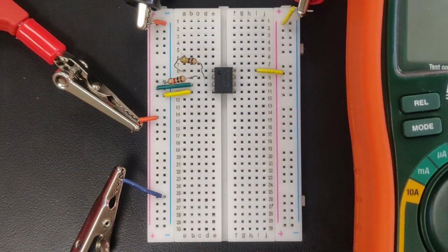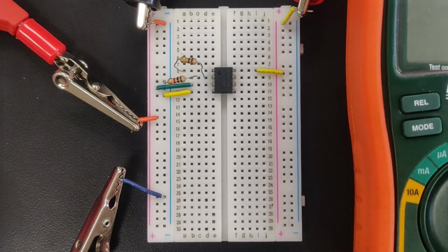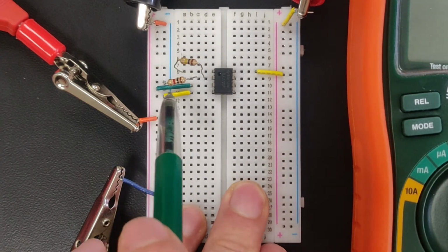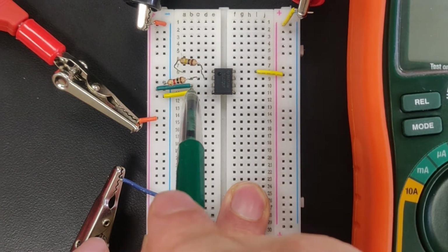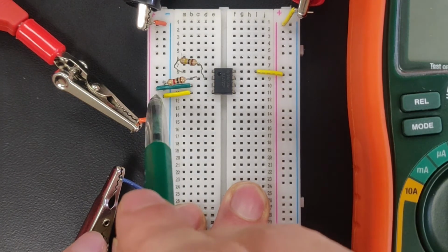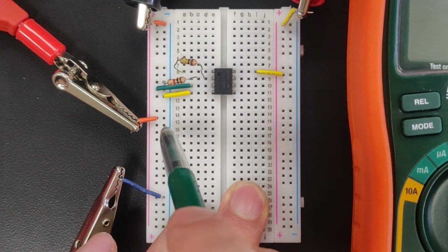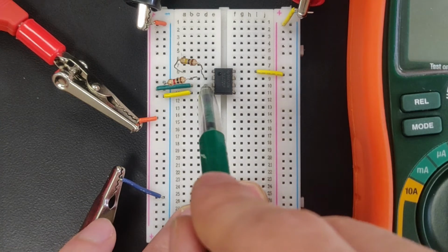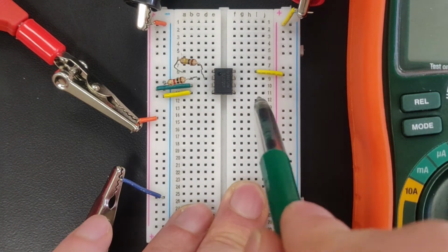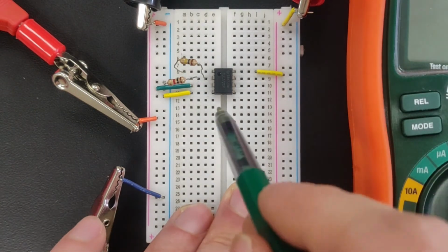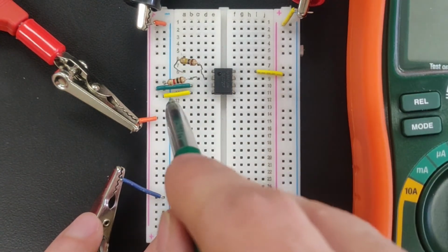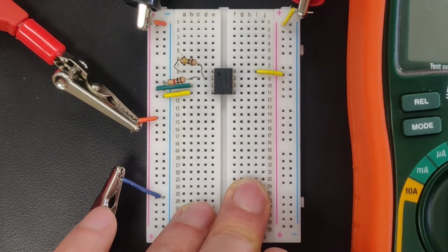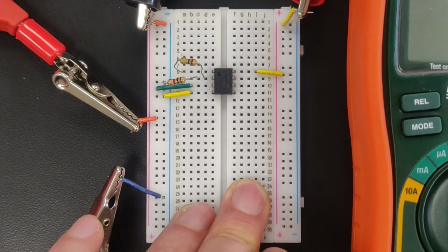All right, here is our non-inverting amplifier for part C. So, main distinctions now is that our positive Vin is being tied directly to the input, so AC input signal on the left going into our positive Vin pin. And now our negative Vin is tied to ground with this 1000 ohm resistor, and it's still the same 1000 ohm resistor from last time, so it's 985 ohms.